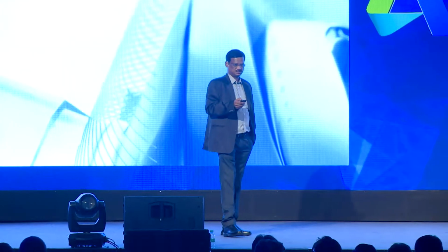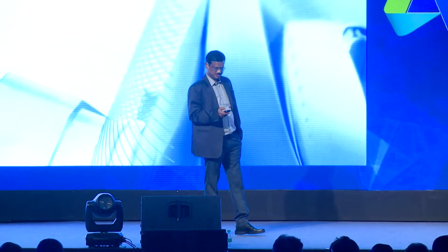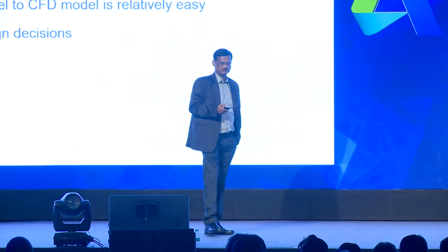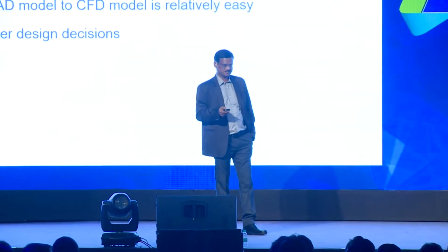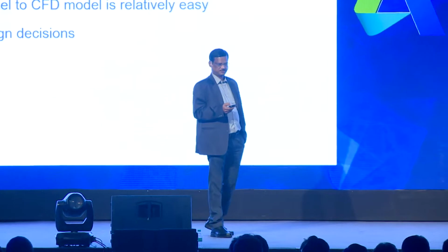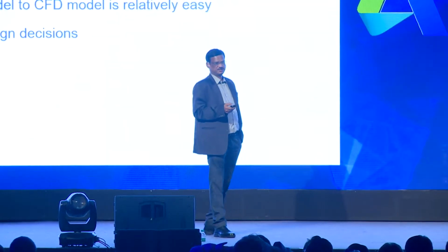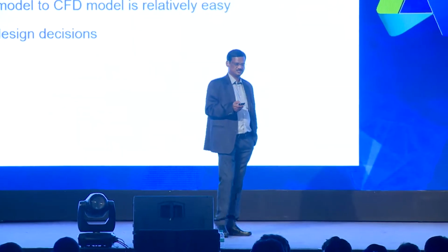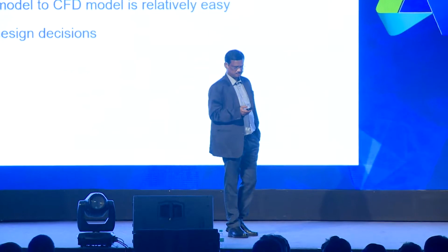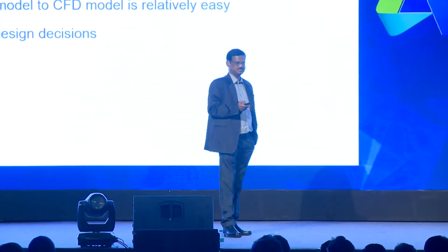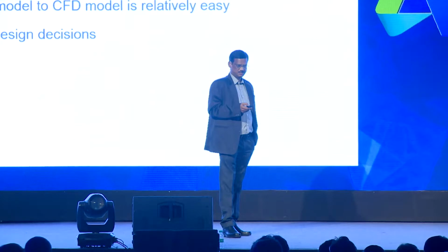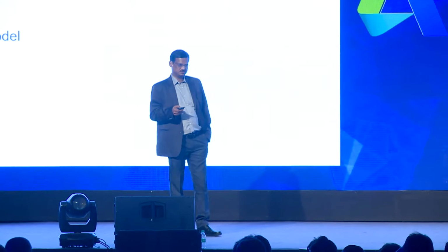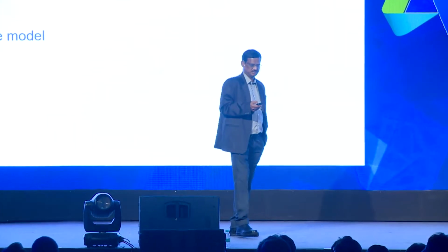And I'll just touch base on the advantages and limitations of using Autodesk CFD, more benefits than limitations. It's easy to use, and we can quickly validate the design for smoke control strategy. And it's an engineering-based and performance-based approach. The interface with Revit for getting the CAD model for CFD is relatively easy, not so easy, but relatively easy. And CFD analysis gives more insight into the design, so you'll be able to understand, optimize, and innovate the design.